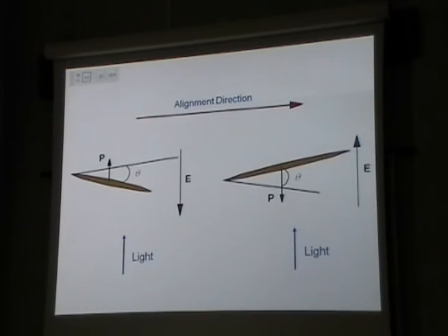If I reverse the electric field, what happens? I'm no longer in equilibrium, my dipole has to move, my lever effectively turns the molecule round, and in doing so I rotate it. When these liquid crystals are tilted, I rotate it through its tilt to give me a different orientation of my molecule, but now through this angle theta.